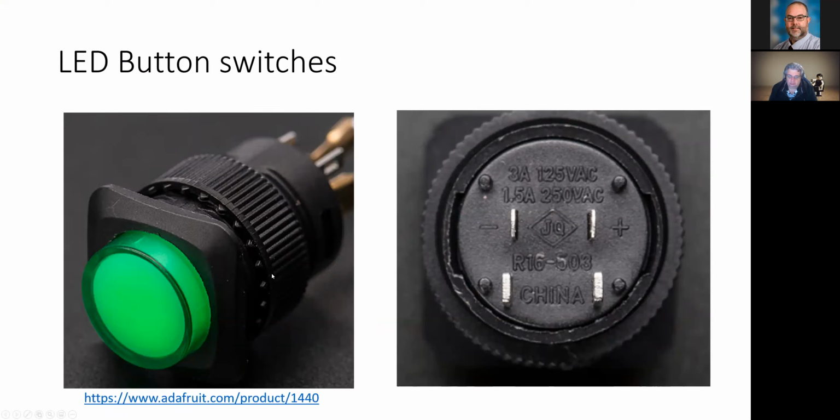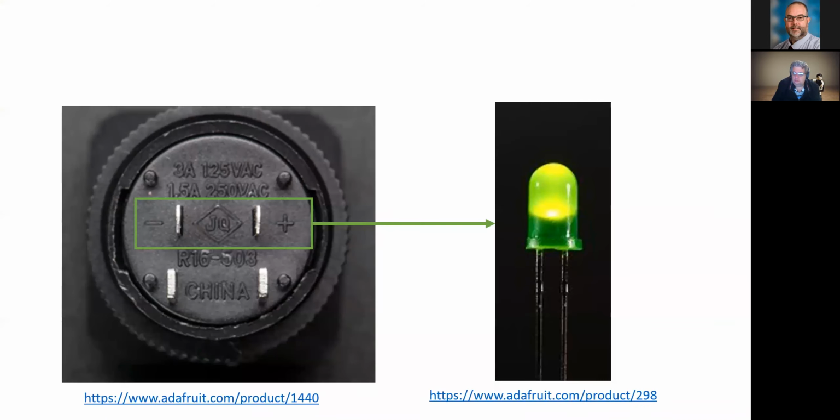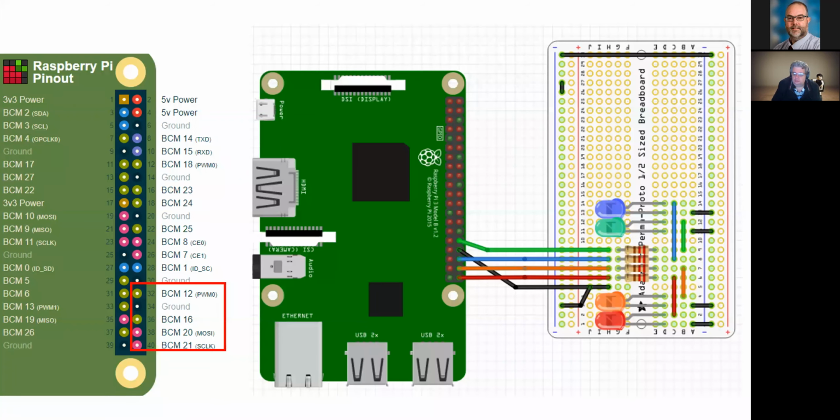And I learned another lesson: don't order just the number of parts you need, because you will lose, break, or kill something. One of the first things I learned was these don't have a resistor to protect the LED. So as soon as I plugged it in, I blew the LED, and you can't replace it. And I had to wait 3 weeks for another one. That wasn't so much fun. So yeah, those 2, just basically a little LED. So that's how I built it.